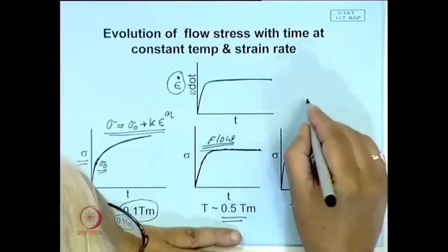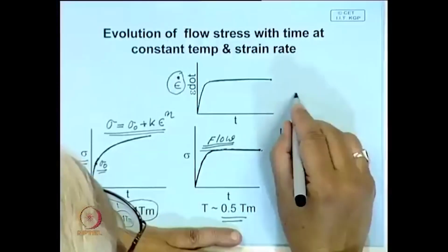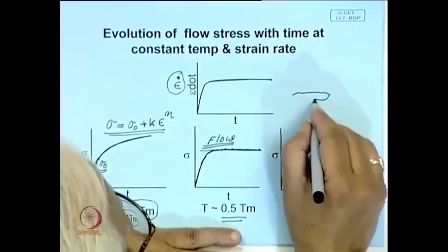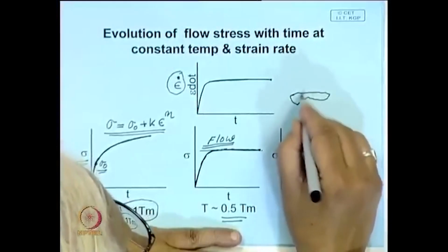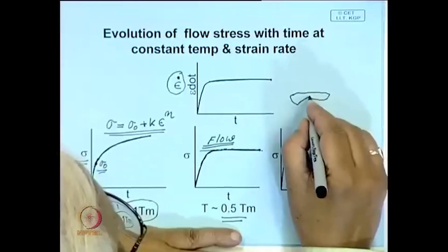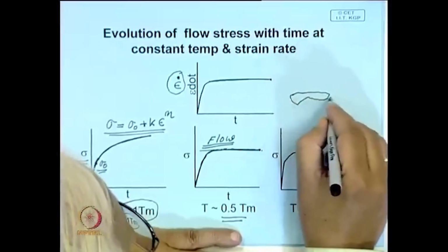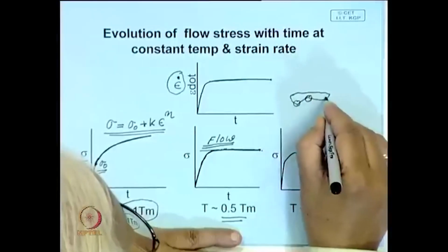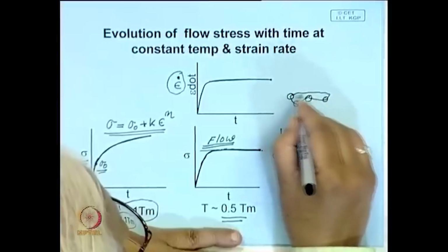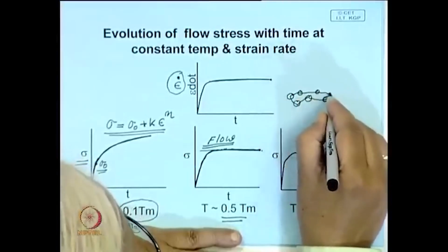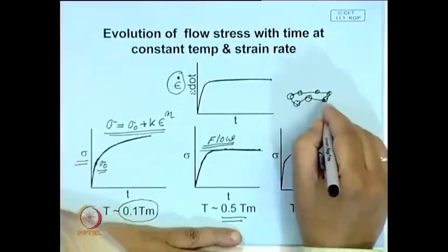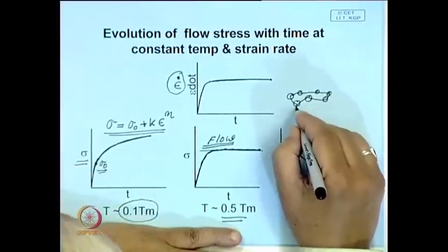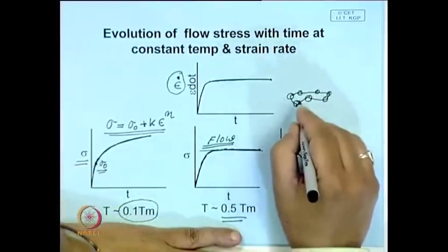And in the other case, where the material behavior is such that the energy in the deformed grain exceeds a critical energy, recrystallization starts. Strain-free grains nucleate at the grain boundary and keep on growing, and when these strain-free grains develop, their strength is low.